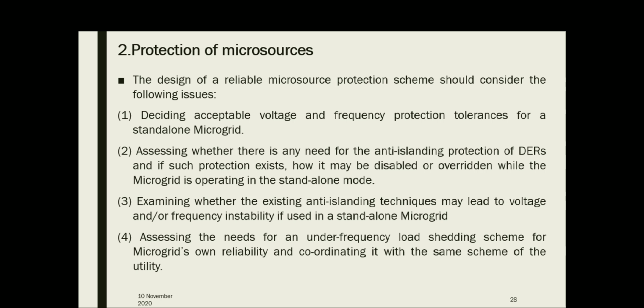Third is examining whether the existing anti-islanding technique may lead to voltage or frequency instability if used in a standalone microgrid. And fourth is assessing the need for an under frequency load shedding scheme for microgrids on reliability and coordinating it with the same scheme of the utility.